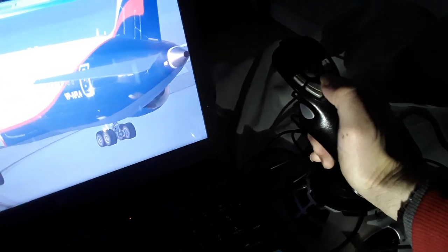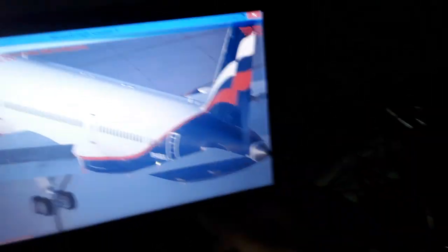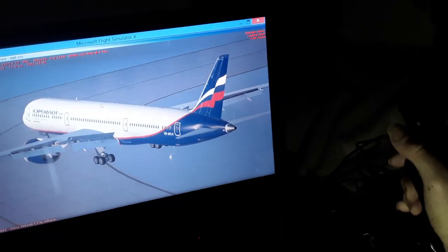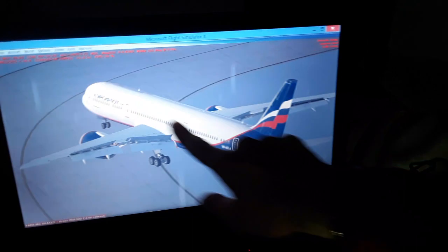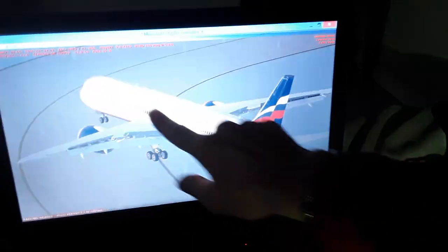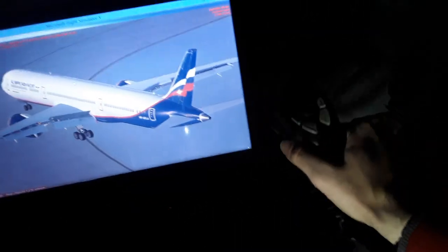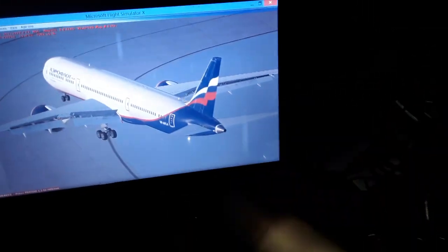You have also the horizontal trim stabilizer, so you can trim the elevator as you fly, or the stabilizer. So you have the elevator, the pitch axis, the yawing axis. We have also the longitudinal axis here from nose to tail. The other axis is the roll axis. You can make left and right turns using the ailerons, the spoilers, and the flaperons. So you can see the yawing axis like this, left and right turn.